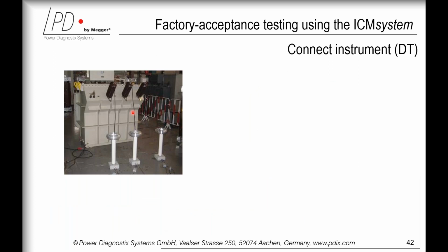The divided voltage signal is used for measuring the test voltage and for synchronizing the PRPD. Important remark here: without proper synchronization, any PRPD recorded during the measurement itself is useless. So this voltage signal has to be connected as well.